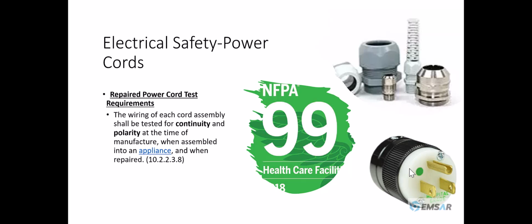green or ground wire in that just a couple millimeters longer than the hot and the neutral. And you want to make sure also that you've got this cord cap tightened down on the insulation. If you have wires showing, then you'll have to cut it back and rewire it again to make sure that when you close it up it is on the insulation and not pressing down on those wires, creating another hazard.